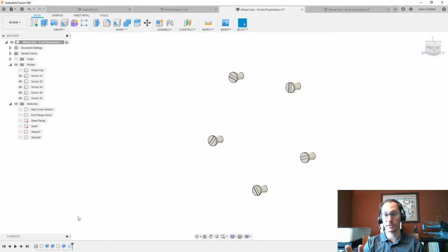I'm going to summarize for a second because that was a lot of stuff, right? The first thing I showed you was the difference between history and no history. I also showed you how you can take a model that has no history and turn that history on, create new features in that history, and still go back to that base feature and make changes to it.